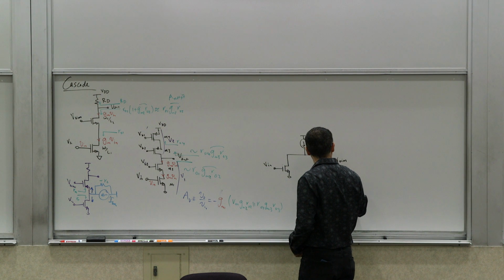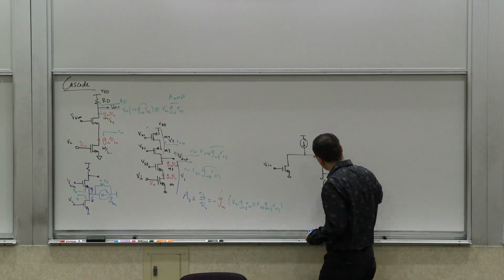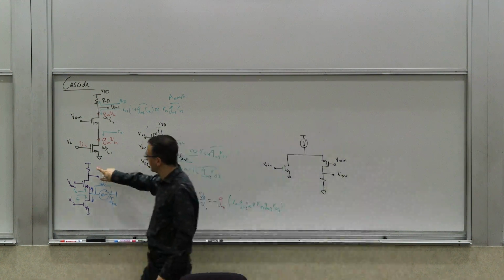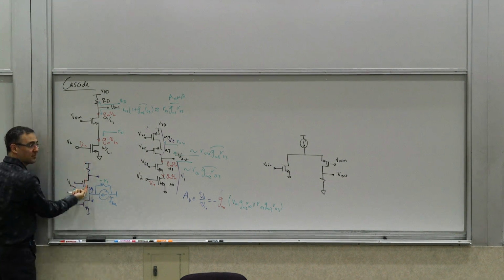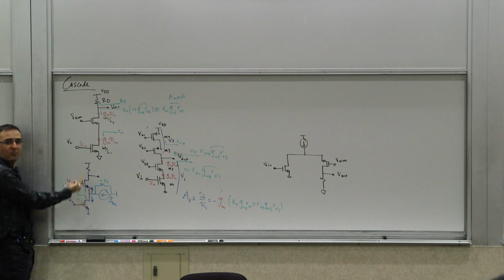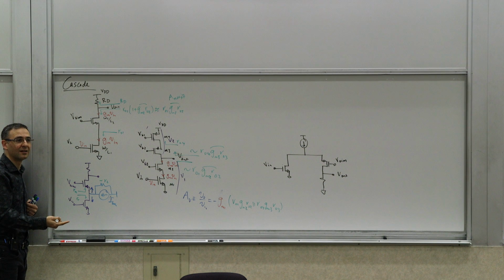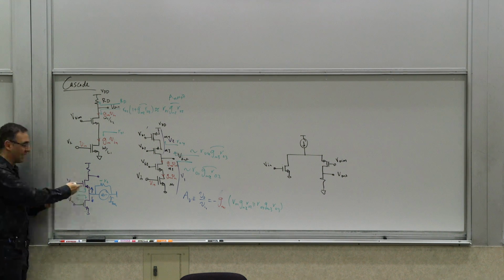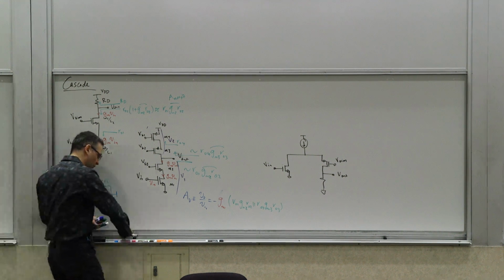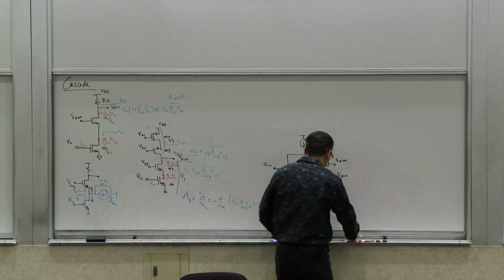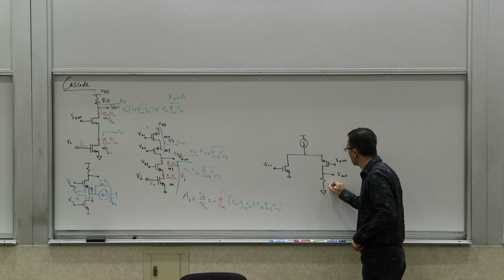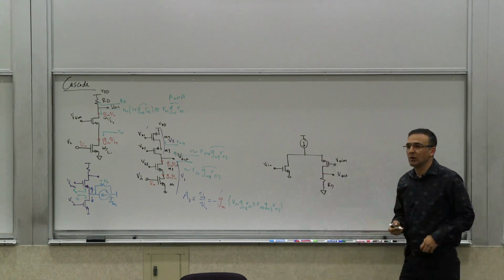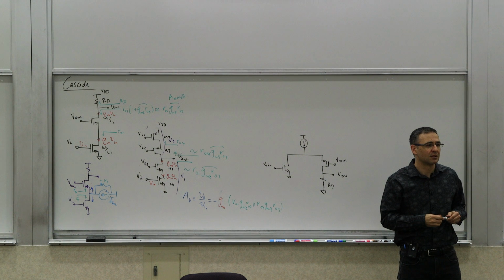Now here's the same thing, right? The only difference here is that I also had to make another change to my R. Because if this resistor goes to VDD, then it can't sink current. Remember, current wants to go upward, and if this is VDD, it means this voltage has to go above VDD, which in this kind of operation it cannot. There are some circuits you can design that push it up, but at this point, it can't. So it has to be referenced to ground. But from an AC perspective, it's not going to make any difference, so this is still going to be RD. So this is what we call folded cascode, right?